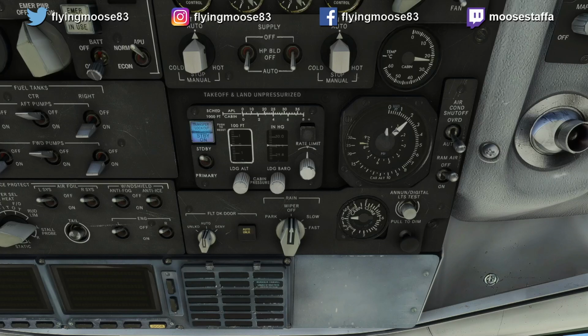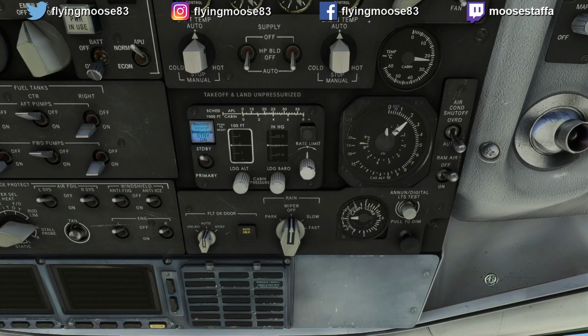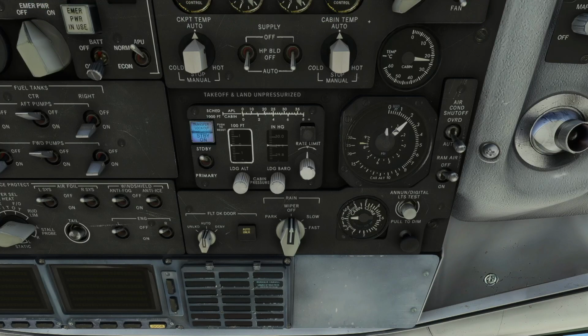And what this does is in flight, imagine you're flying along and you have some kind of an issue or problem with your pressurization controller and it needs to switch to standby. You don't want it automatically switching back to the primary that's broken, or if you switch it back to primary and the standby is the problem, you don't want the system automatically switching it back to the broken controller. And so it automatically goes to a transfer lockout, and you push this to reset that.